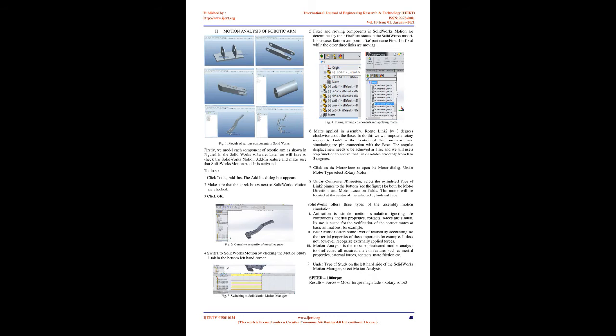9. The new formulation method is based on screw theory and quaternion algebra. Screw theory is efficient to establish a global description of a rigid body and avoid singularities due to the utilization of local coordinates. The dual quaternion, the most compact and efficient dual operator to a screw displacement, was used as a screw motion operator to get the formulation in a compact closed form. Inverse kinematic solutions were obtained using Paden-Kahan subproblems.